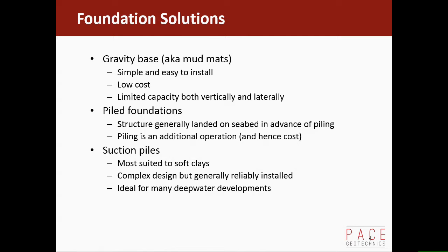Piled structures do give you more vertical capacity, and much higher lateral capacity, but you still often have to land the structure on the seabed and then you put the piles in. You don't land the structure on the piles. So you still have a gravity base to design. I'll explain it a bit more as I go.